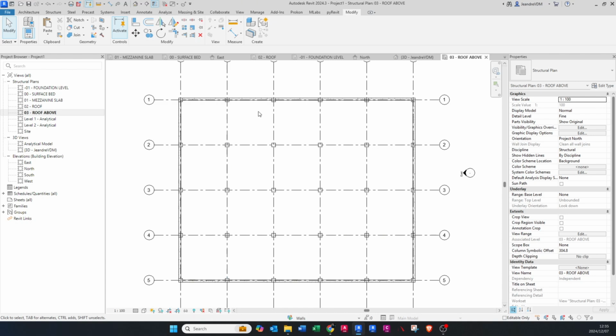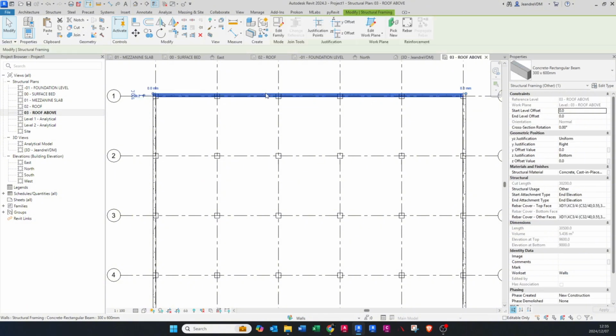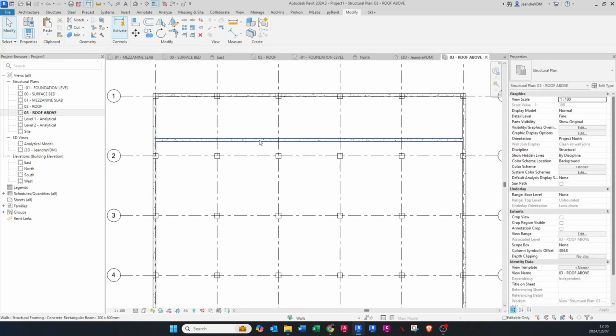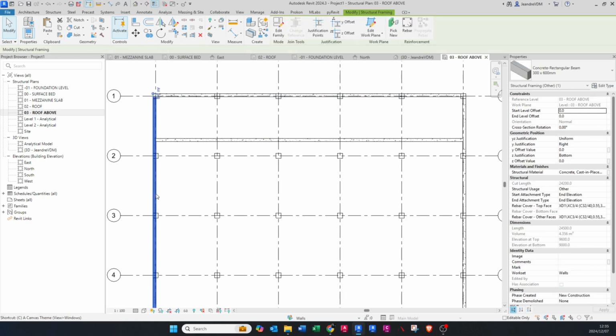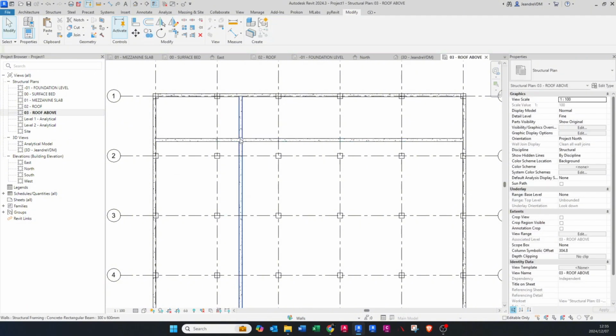So I'm going to just run through some of them. Let's start with the copy again. If I click on this, I say copy, and I bring it down to that plane on the layout. Now, let's say I'm going to draw in another beam. Let's take that beam and copy it over to here. Now I want this corner to meet; I don't want it to protrude through.